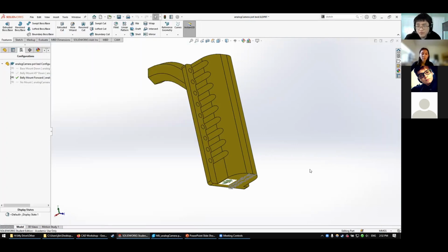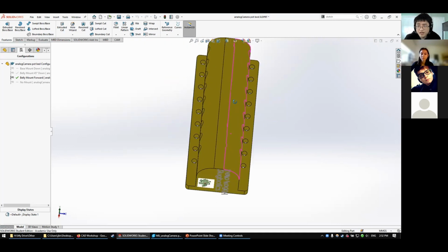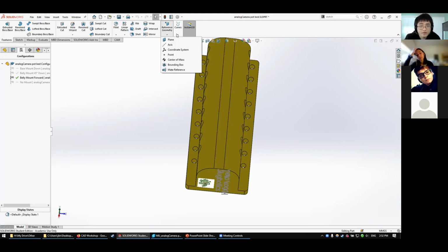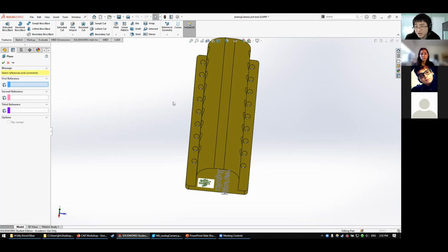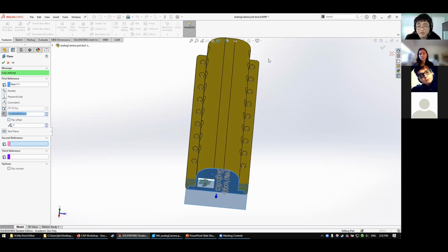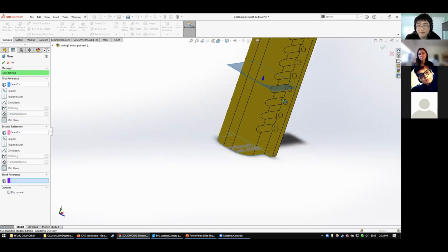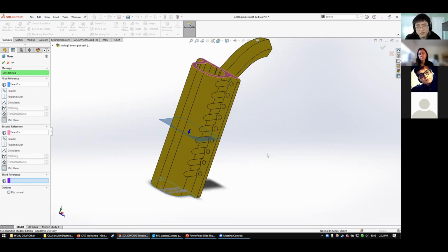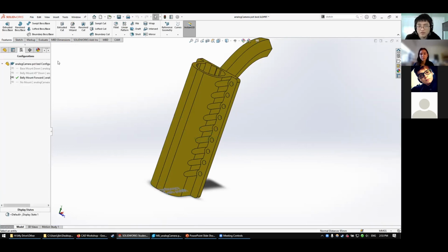Reference geometry is super important for when you're making pretty much anything, because you will want to say, I want this hole to be within these 2 points or in the center of these 2 planes, whatever. When making planes, as you have seen on Naomi's screen, there are a lot of different options here. You can have up to 3 references. Most of the time, you only need 2 references, but sometimes you can need 3. So if you just select one plane, you say, I want an offset from this plane this much, or you can select 2 opposite planes, and it'll give you the mid plane. So play around with these, and you can get a bunch of different weird combinations that will allow you to define where the plane is, where there's intersecting stuff, in between 2 stuff, intersection of 3 lines, whatever. But there are lots of different ways you can do reference geometry.